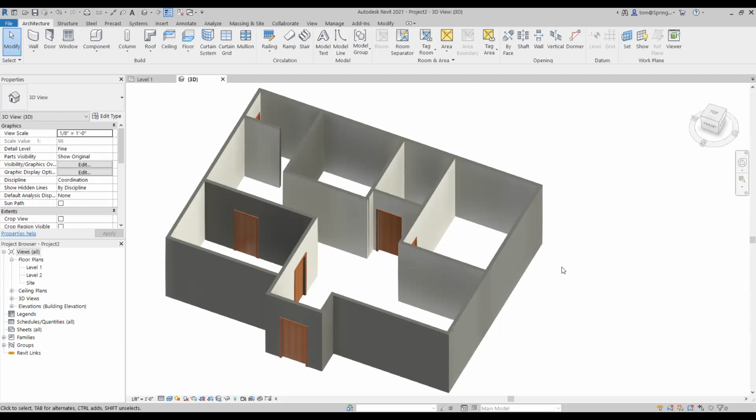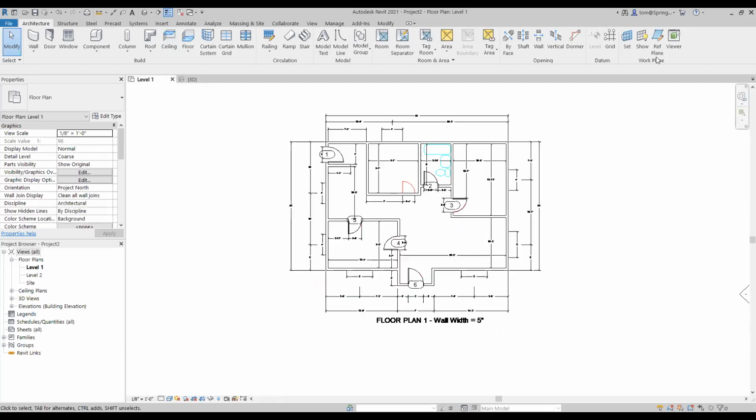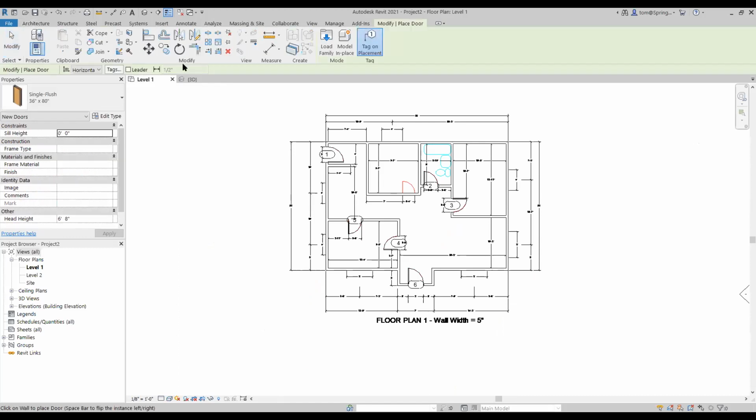Quick question, will it automatically generate numbers for that, or do we have to input those every time? It will, well, actually, you just have to tell it to tag them. If you tell it to tag them, it will do it. So when you get into the door, for instance, right here, you have the option of tagging it or not tagging it. And then you can also set the number where it's going to start so they sequence up. Okay? Good. That makes sense? Yes.